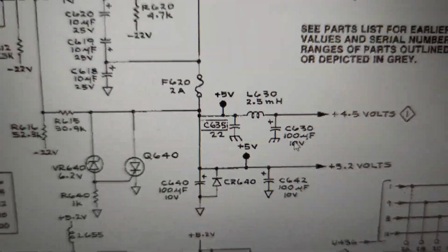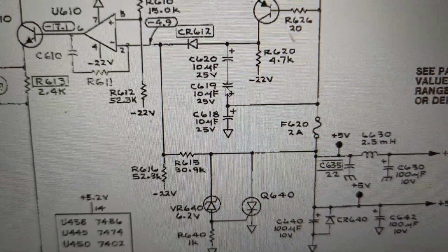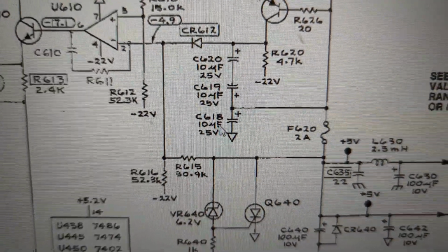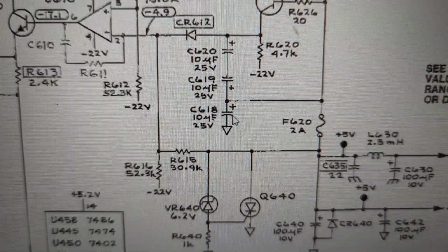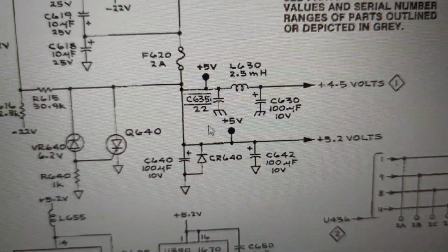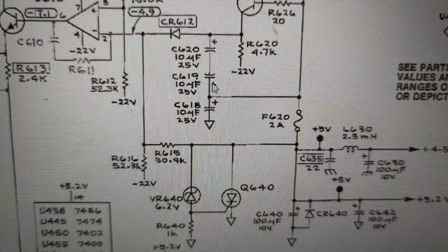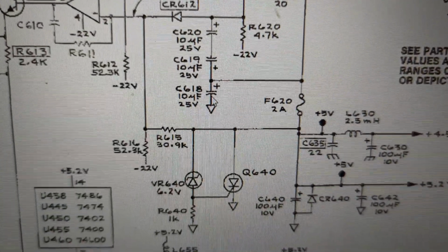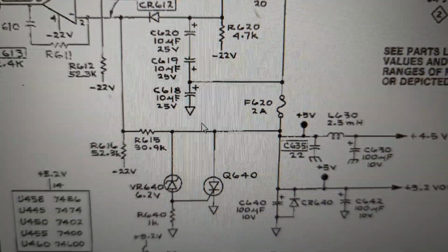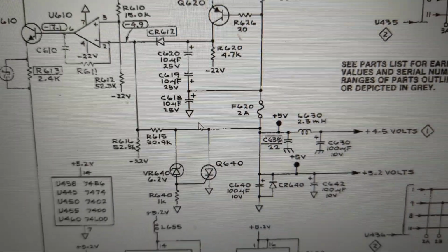I know tantalum caps are notorious for going bad, and I definitely have these values. It's only 5 of them, so I think I'll just go ahead and replace them, instead of trying to narrow down which one could be causing a problem, if any of them are. I'll do that and see if it changes anything.